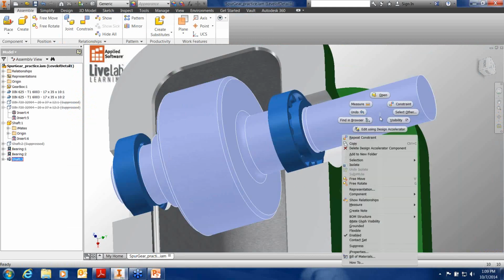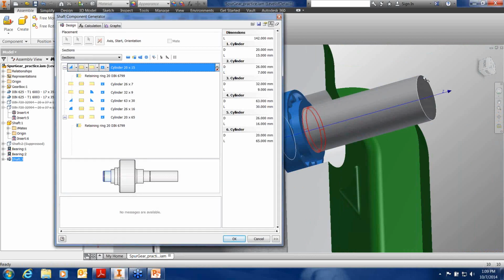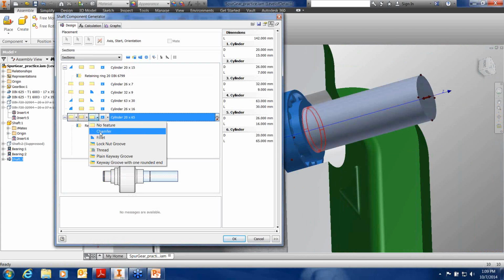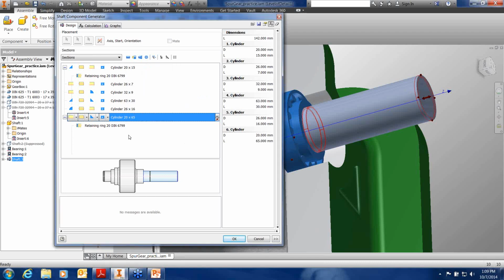Okay, let's come back now to our final piece here, the last cylinder that we added. I've got a couple more things I want to add to it. I want to put a key slot on it as well. Now, let's go ahead and finish off this edge here and put a fillet on it as well. So I could come in here, or a chamfer on it as well. And again, this time I'll just do a 1 millimeter instead of a 1.5 millimeters. Let's check it, see my preview.